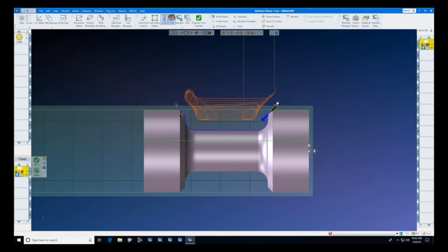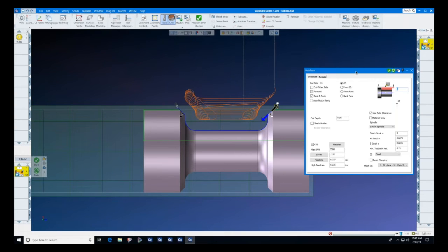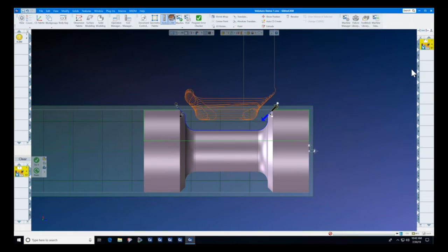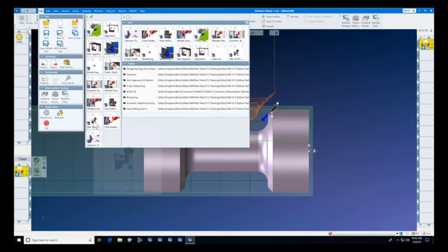So volume mill turning combined with the capability of our new B-axis milling machine lathes, and it's a milling machine and a lathe welded together, allows us to cut, number one, tough materials or soft materials, but we can cut more efficiently inside of confined areas with round inserts. And again, we can double our production and increase our tool life. Volume turn. Let's go and look at our demo here for a Swiss machine.